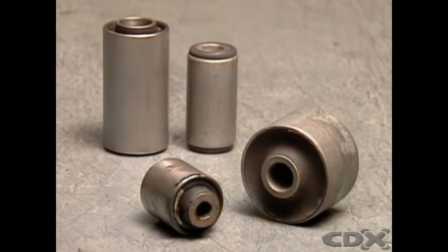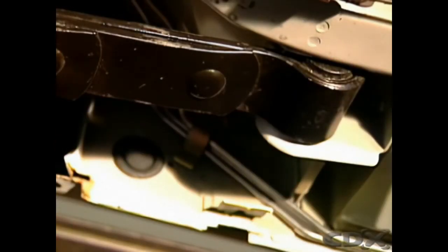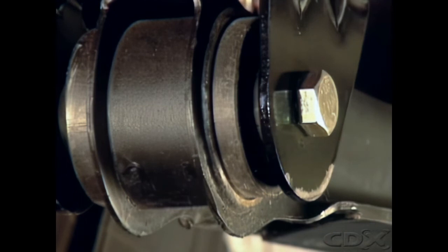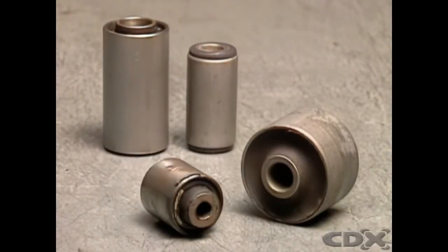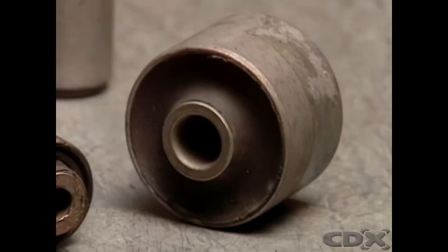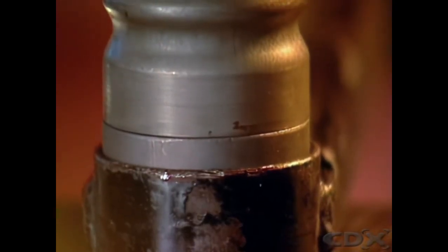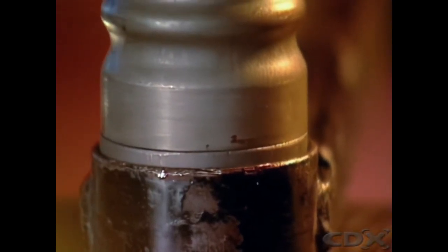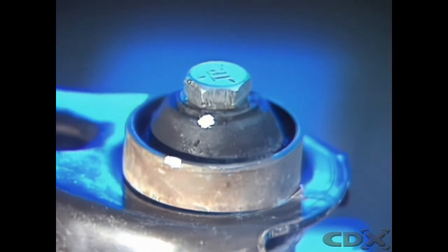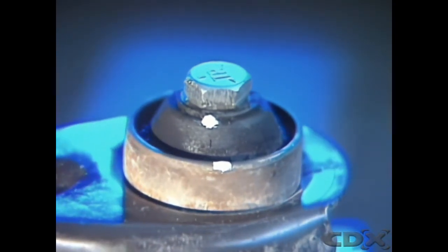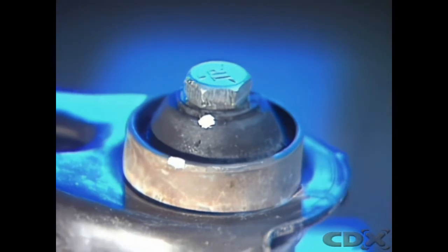Metalastic or rubber bonded bushings are normally used for the front eye of the spring at the fixed shackle point, and also in control arm applications. The bushing has a steel outer casing and inner sleeve. The rubber medium is bonded to both to provide flexibility between them. The outer casing is normally pressed into place in the component. Relative movement between the casing and the inner sleeve causes the rubber to shear without tearing.